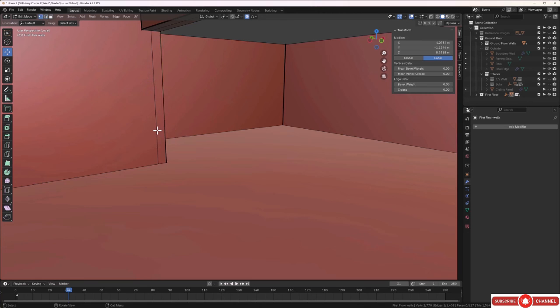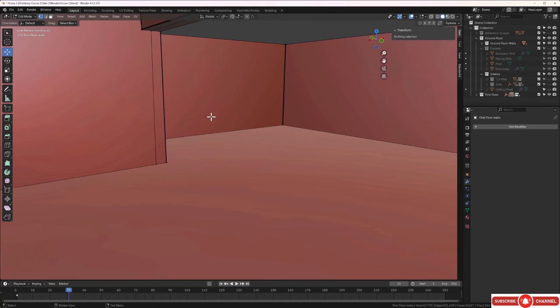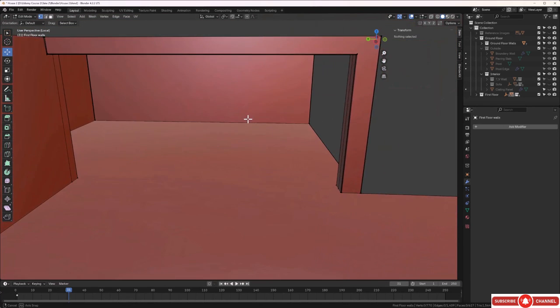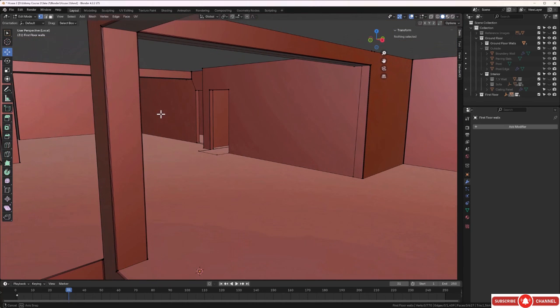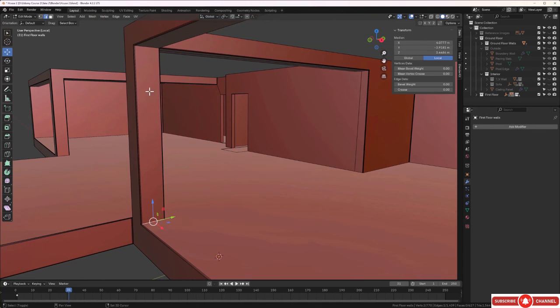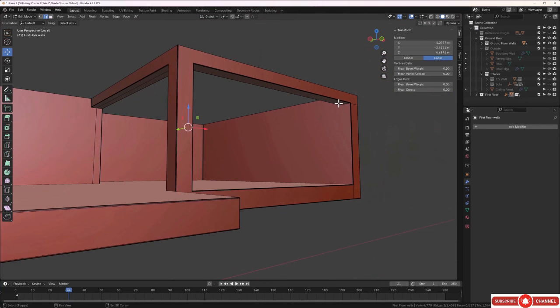And if we wanted to, we can press 1, grab this vertex here and just pull that over. Whoops, I will turn off proportional editing. And now I can pull that over if I need to, just to square that up if necessary. Okay, so where next? So we've done that one. So now I'll press 2, and I'll grab maybe this edge here, and I'll hold shift and grab maybe this edge, and I'll also grab this edge, and I'll press Ctrl R and see if we can get a loop. And we can, that's worked.